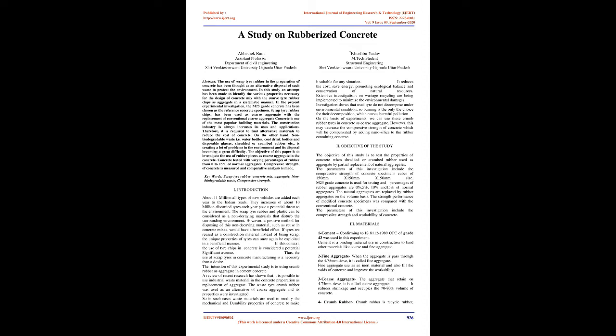On the other hand, non-biodegradable waste, i.e. water bottles, cool drink bottles, disposable glasses, shredded or crumbed rubber etc., is creating a lot of problems in the environment and its disposal is becoming a great difficulty. The objective of this paper is to investigate the use of rubber pieces as coarse aggregate in concrete. Concrete is tested with varying percentages of rubber from 0 to 15% of normal aggregates. Compressive strength of concrete is measured and comparative analysis is made. Keywords: scrap tire rubber, concrete mix, aggregate, non-biodegradable waste, compressive strength.